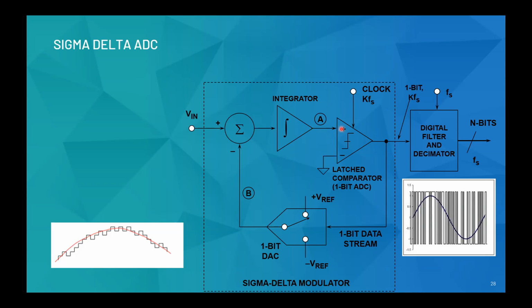So the shape of the analog signal is transmitted as follows. A 1 basically indicates a positive excursion has occurred in your last sample, and a 0 indicates that a negative excursion has happened. So the output of a sigma delta is more like a bit stream, right? If the input doesn't change, the bit stream would be alternating ones and zeros, 0, 1, 0, 1, 0, 1. If it is going on increasing, then it may be a set of high, high, high. That would be the bit stream. If it's going low, it's going to be the other way.